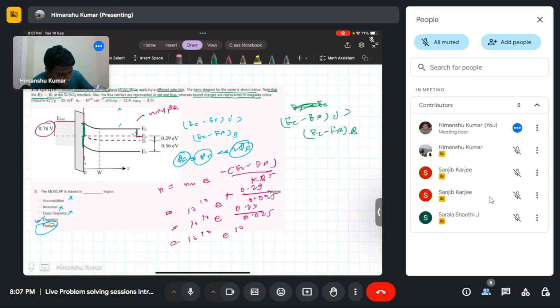So basically it is less N-type compared to the bulk. Another way to see it is that it is more P-type compared to the bulk. You create more P-type just by removing some electrons out of this interface region. So some electrons are pulled out of this region. That is why it becomes less N-type and more P-type, and it is becoming depleted.